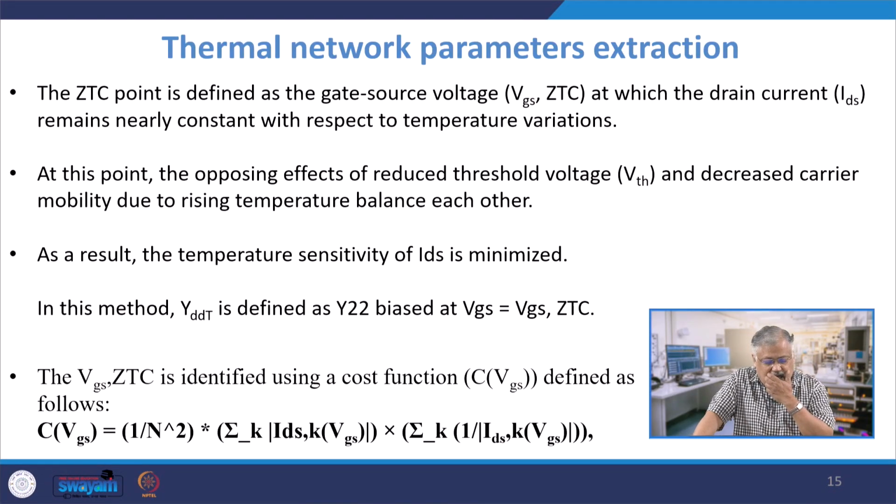With this discussion, as I discussed with you, the ZTC point is defined as the gate to source voltage point at which the current remains nearly constant, independent of the temperature variation.